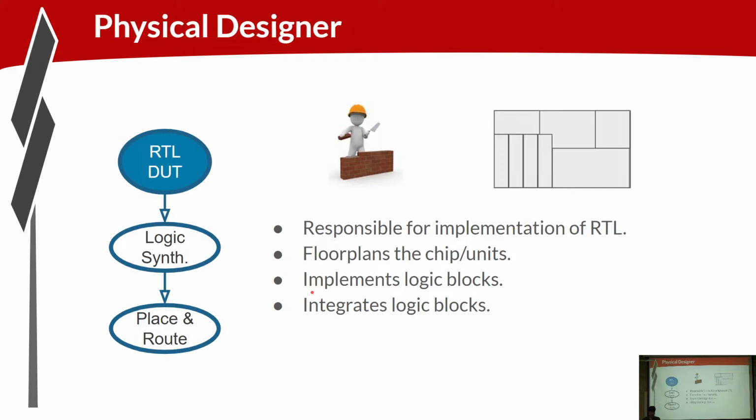And so the physical designer, and we're going to come back more to the verification role since it is so intricate, but the physical designer is fed the RTL. They run logic synthesis, place and route. Right? So logic synthesis is coming up with the gate level model, and then place and route is placing the gates physically across the silicon area that's available and connecting up the gates.